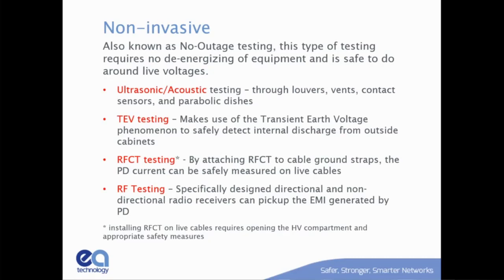They also have some instances where they'll go to do a VLF offline test and they apply a voltage that's 2 or 3 times the rated voltage or nominal voltage, and it fails. Well, if your cable fails at 2 times nominal voltage, it had a defect. That stuff should work a lot higher than that. So you might end up where you see a failure, customer's going to blame it on your testing, but what happened is your testing really brought out a defect that was there.